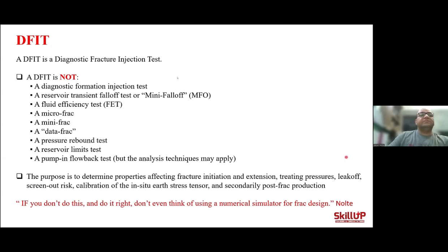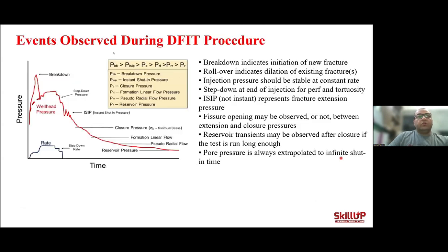So what are the events observed during a DFIT procedure? First of all, you will observe something like this. This is a breakdown pressure, a sudden drop in pressure. This means that you already broke the formation. If you didn't get this and you get something like this, a smooth curve of pressure buildup,